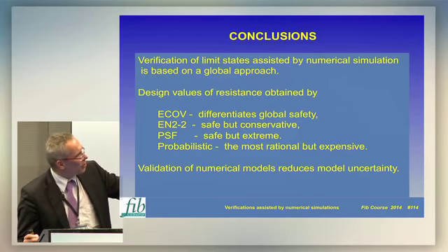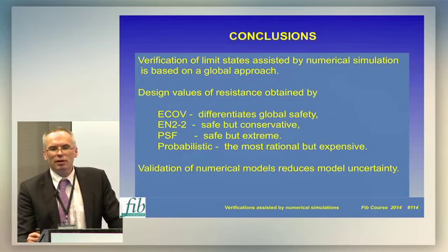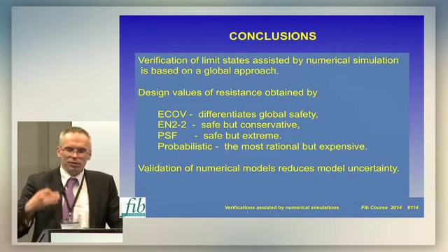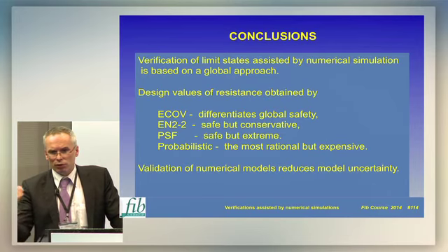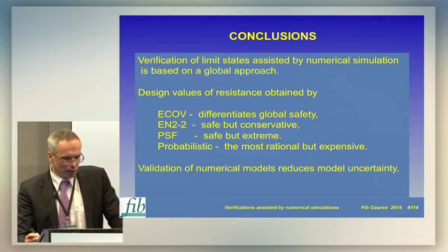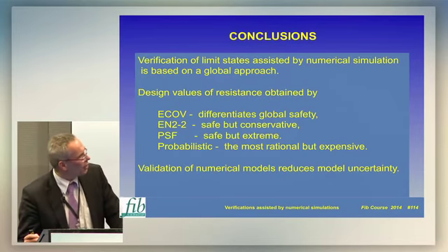The ECOF would be the second method, which already introduces some probabilistic approaches, but it is probably still a little bit more demanding, so it will be used probably in the most extreme situations or for safety critical structures. Otherwise, the PSF method or the Eurocode method are the most suitable.